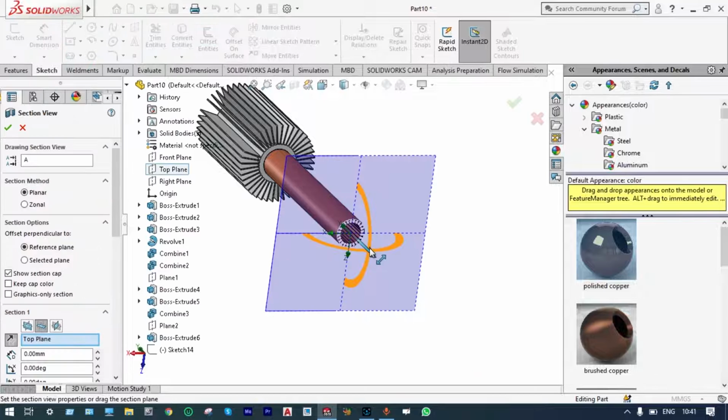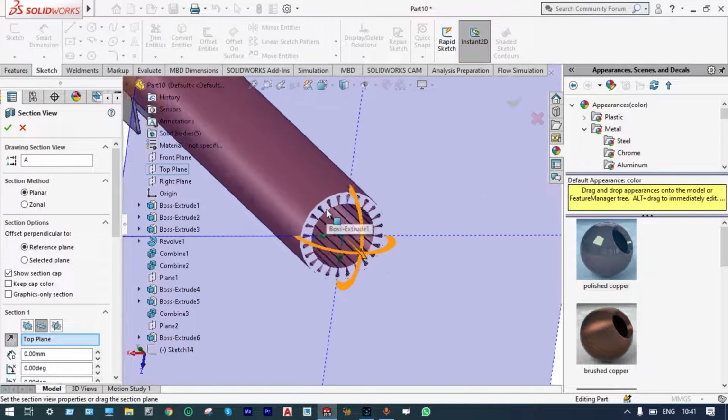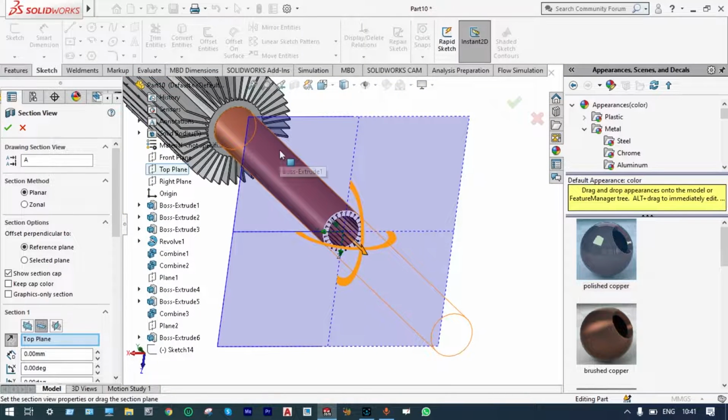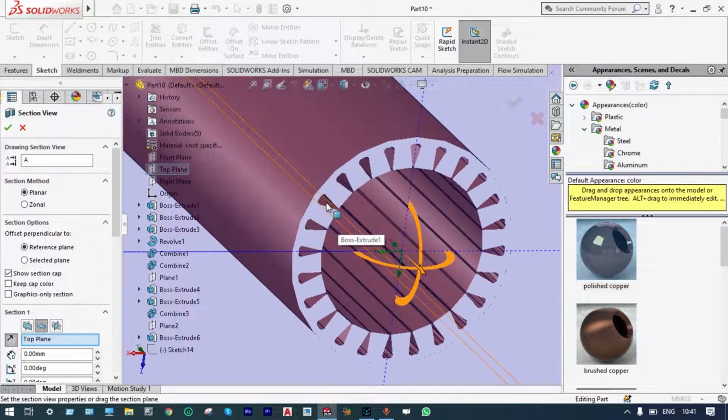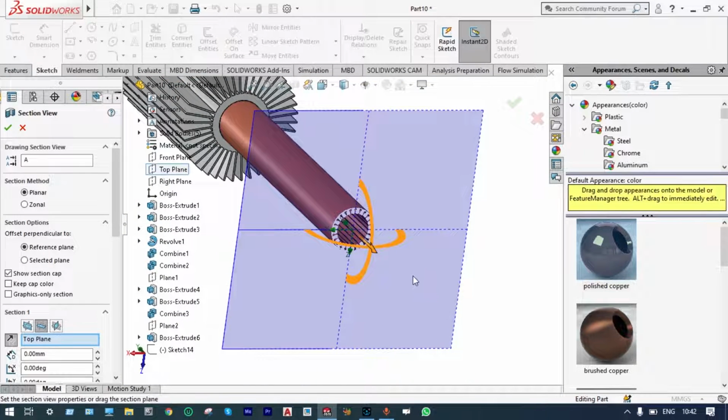So initially we will provide heat at the evaporator part. A little amount of water will be there at the bottom. As it gets heated, it will evaporate and pass from the bottom part to the upper part. After going to the upper part, it will come back through these spaces. So there will be a continuous flow of fluid from down to top, and again from top to bottom, coming again and again.